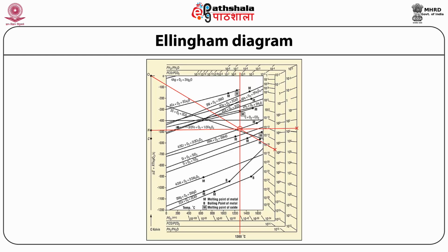We connect the point O provided on the y-axis where temperature is 0 Kelvin to the plot at the temperature of interest and extrapolate to the nomographic scale. It can be noticed that the oxygen partial pressures attained depending on H2/H2O and CO/CO2 ratios can also be plotted on the Ellingham diagram.